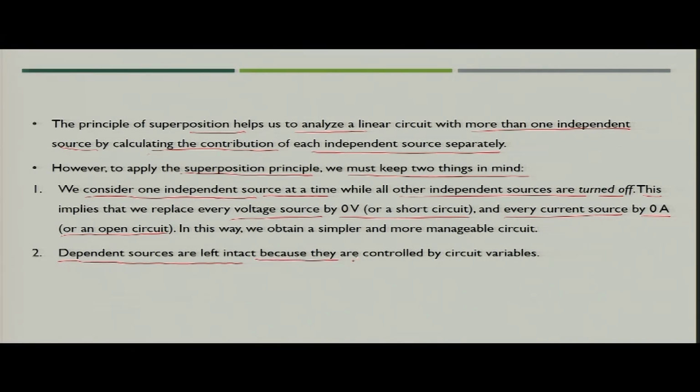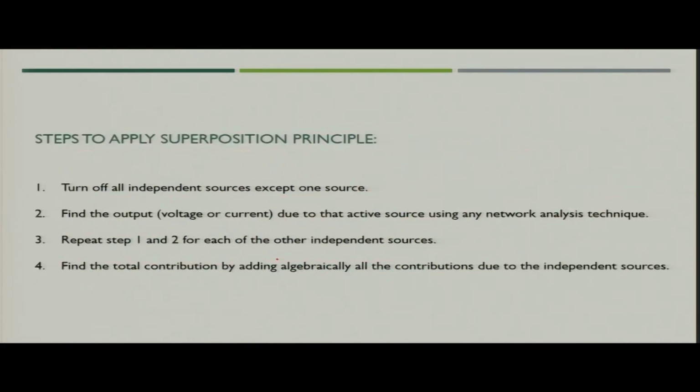The second important thing is that you cannot apply that particular assumption in the case of dependent voltage or current sources, and you have to keep them in the circuit and solve them as you have solved other circuits, like using nodal analysis or mesh analysis. So, dependent sources, maybe voltage or current sources, should be left intact in the circuit.